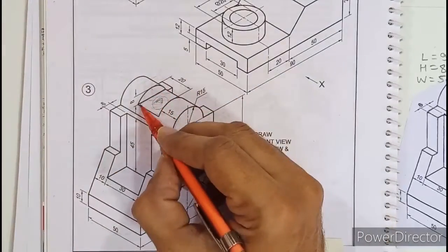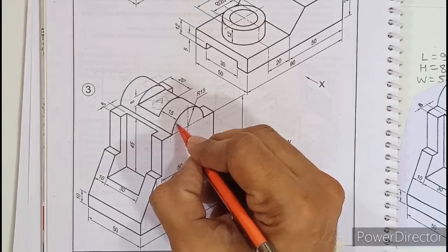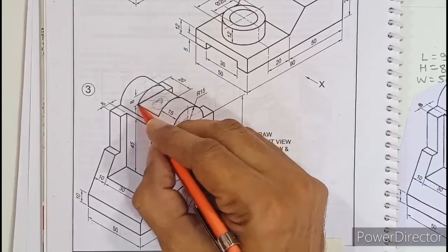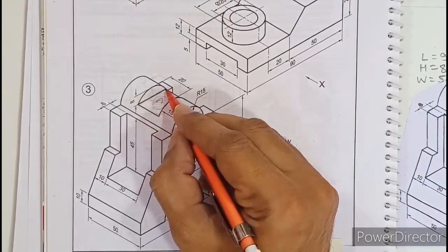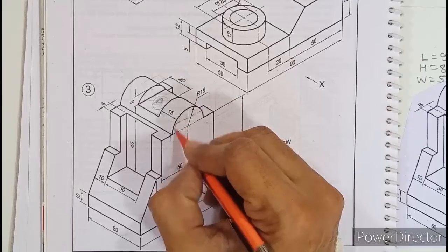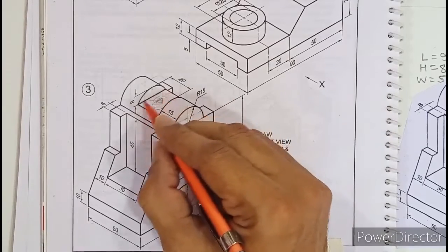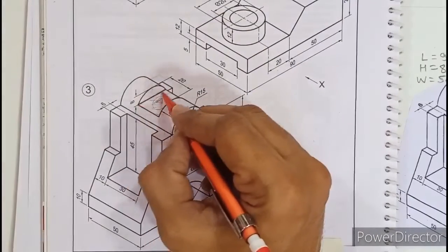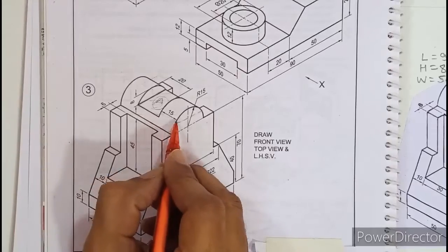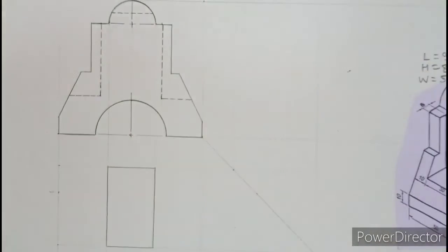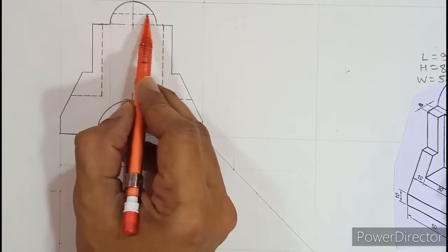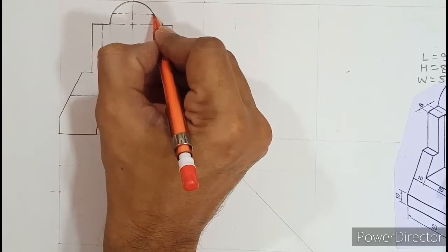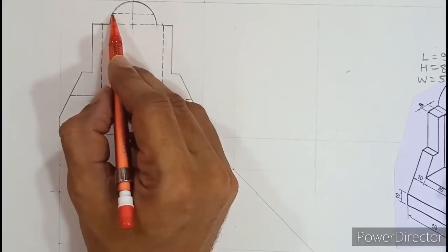If you look thoroughly, the length of this line is the same as the hidden line we had drawn before in the front view, if you can recollect. So this hidden line is the same as this edge, right? Both are the same. This edge you have already drawn in the front view, and if you project these two edges, you will get this length, because it is parallel to 90. So you get the length of this surface A, and the width is nothing but leaving 15 and then 20. In the front view, if you look at this hidden line you drew before, it cuts the semicircle at a point a little bit inside the diameter. This is the diameter, which is wider, and this is a little bit smaller.